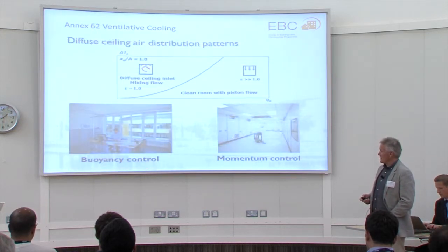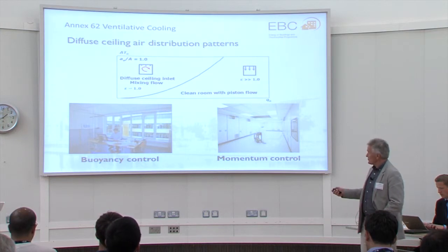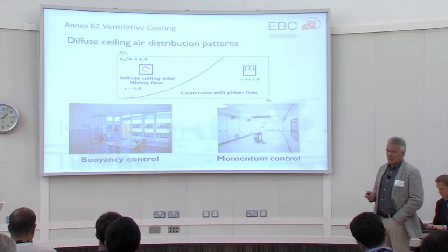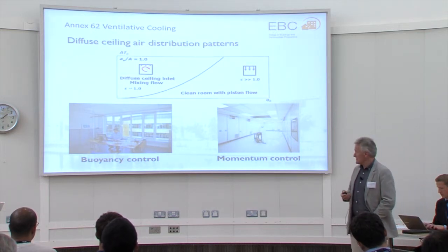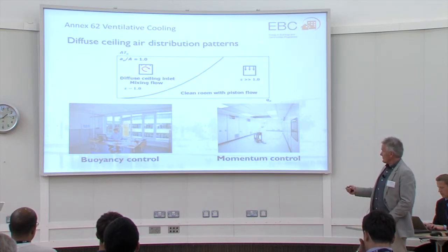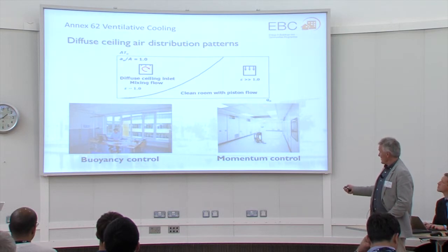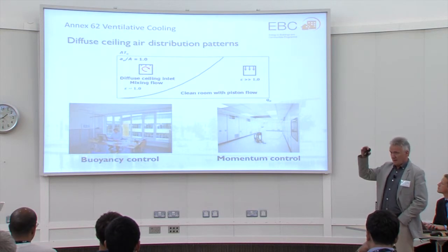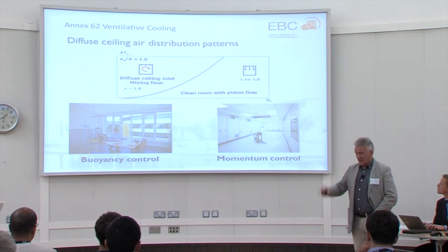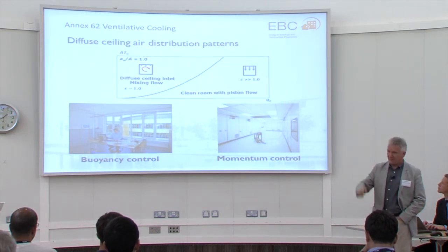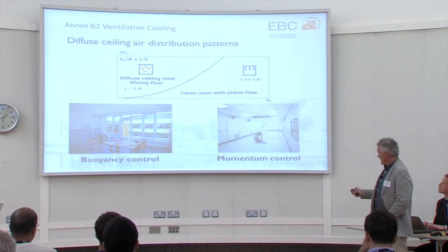Therefore, we have been looking into whether we could use what we call diffuse ceiling air distribution in the offices instead of the normal inlet openings. Of course, we know about diffuse ceiling inlets from clean rooms, where we have a high air velocity in order to have a kind of piston flow in the space. There the air distribution is mainly driven by momentum.